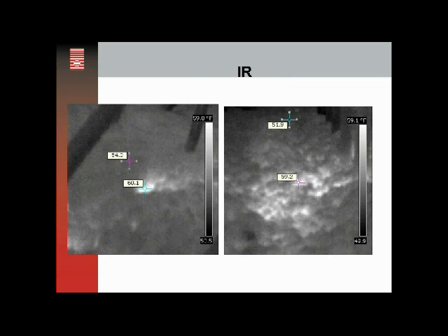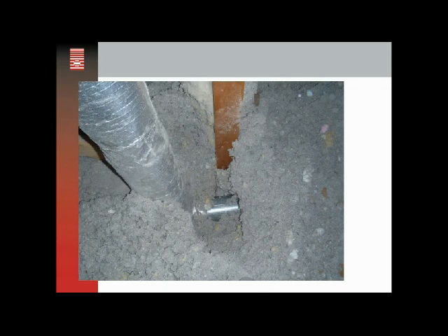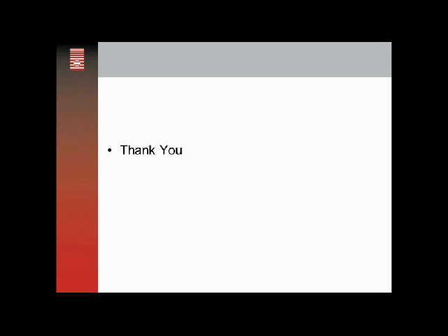Here's a shot of an infrared scan of an attic looking down. You can see that the scanner is picking up hot spots in the insulation, and if you stop and dig it out, you can find potential problems, disconnects or leaks.